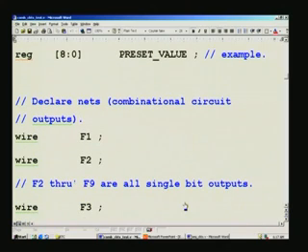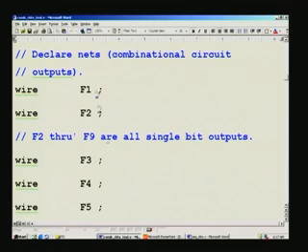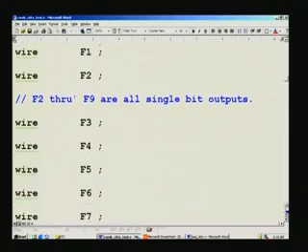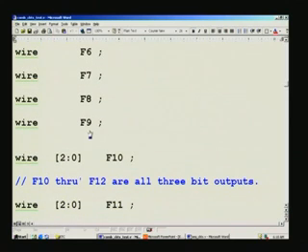And then as far as the outputs are concerned, this is basically a combinational circuit's outputs. So, using either an always block or an assign statement, and here we had to declare it as wire. Why it is a wire we will see a little later on, I will explain why it is so. And we had F1 through F12 earlier for buffer, inverter, etc. I do not have to show it here, and all of them are outputs. So it is declared as wire, we will come to that shortly.